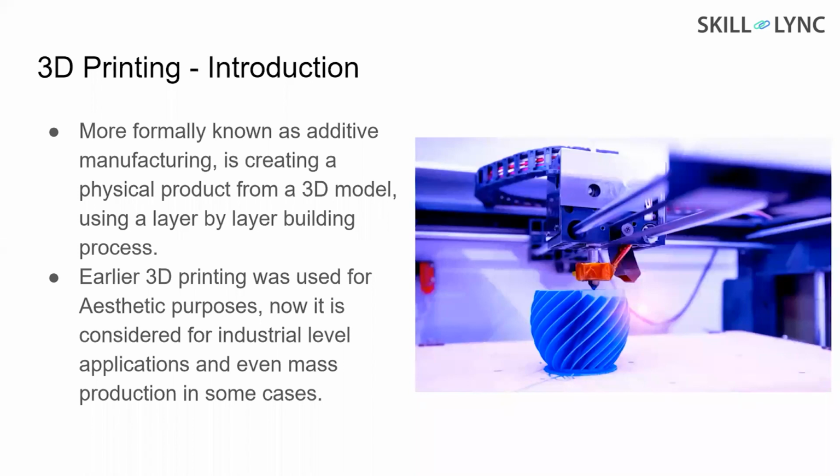But what is the con of that particular type? You have a loss of material. You have a very big chunk, and you're cutting off material. It is time wasting, one of the important things, and it adds to the cost of manufacturing. You're wasting a lot of material. And third, the material which is removed is waste, and this waste should be processed once again and converted into raw material once again. It's a very big process, and you have a lot of wastage.